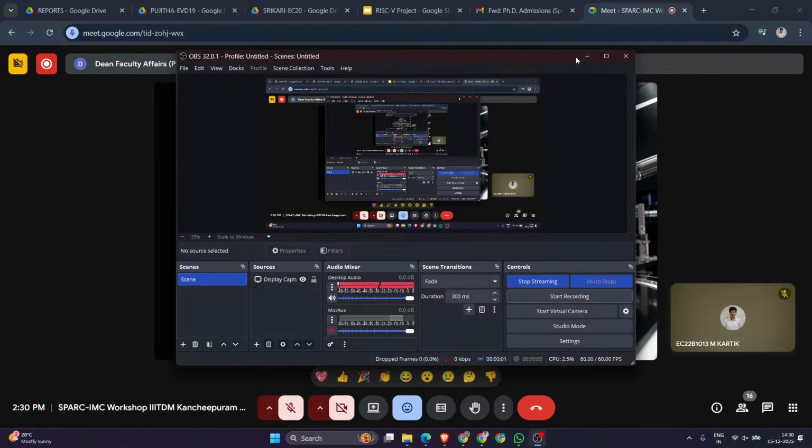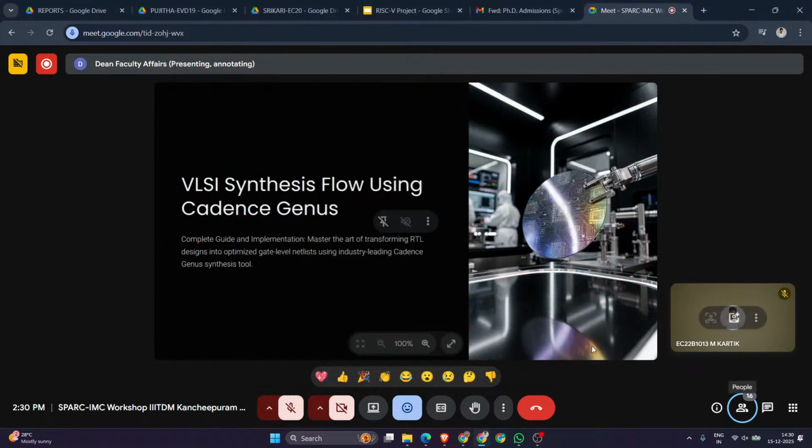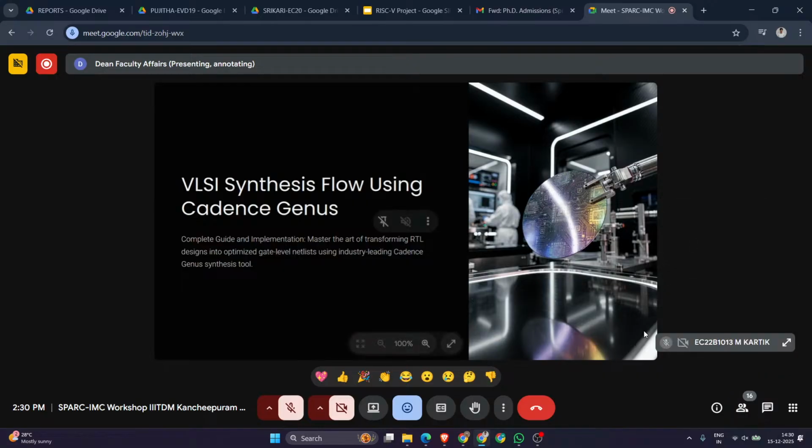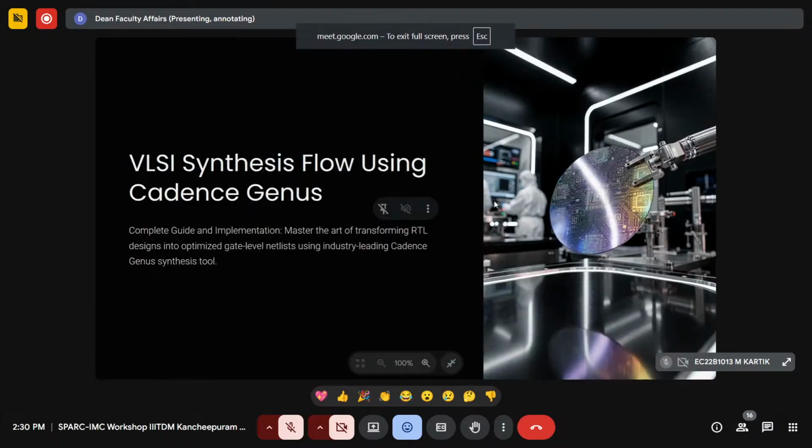Millions of pieces, right? So how a metal to metal should not get shorted, how the physical things work, all the physical characteristics of the design are mentioned in the PDK. So one such file, they call it a technology file. The technology file will say that, hey, in this design, you can use, let's say, 10 to 12 metal layers and you can complete your design.